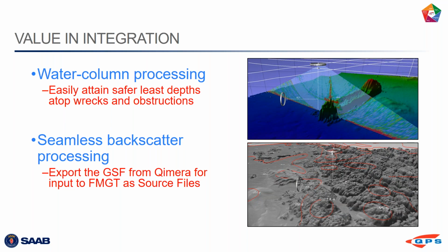Yeah, so my understanding is they want to export the surface overview area as a polygon or shape file, so that they can then use it for the QC in the master project, which is a really good idea. As Matt said, you can export the surface overview edit area, but only as an image, so a JPEG, PNG, TIFF, or EPS, and not currently as a polygon or shape file. Okay. Yeah. All right, thank you.